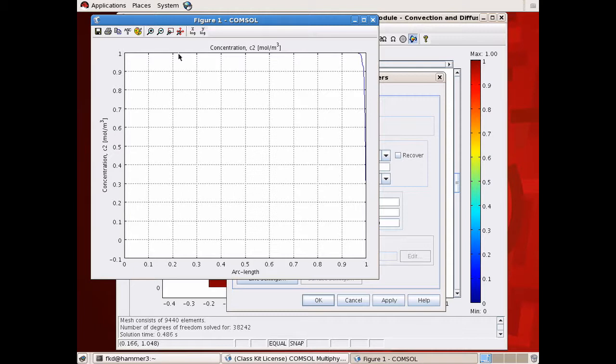The analog, I think, is of something being transported through a flare by some advective velocity, and you have some kind of cross flow in a very permeable layer, which is just shooting across here at some very, very large volumetric flow rate that takes the small portion of dissolved component that emanates from this portion of maybe a low permeability layer, and just washes it out and sets the concentration at that point to zero.